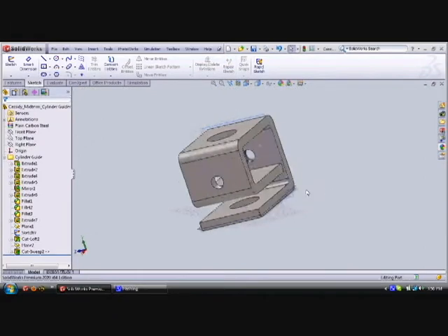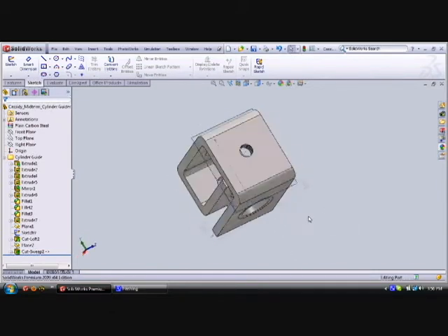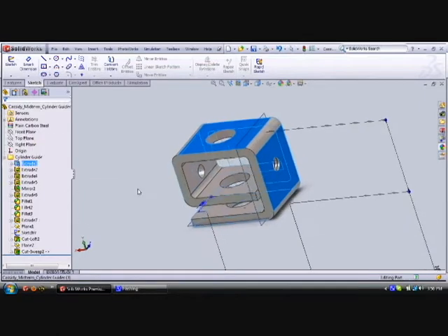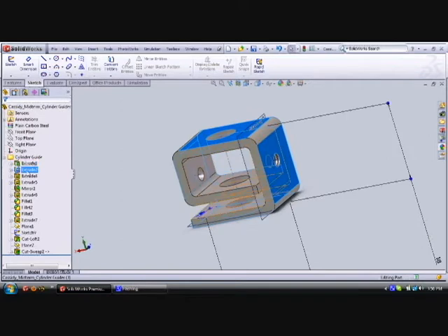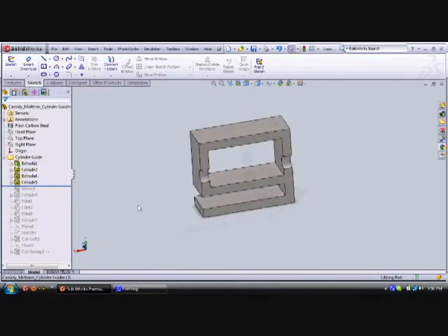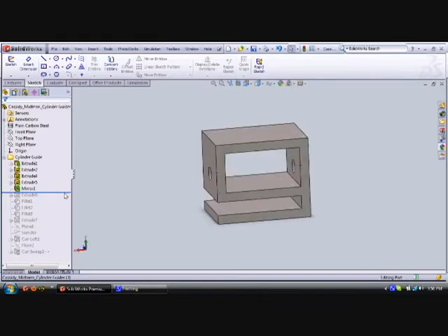The next part I designed was the guide for the cylinder. The cylinder runs through the middle, then actually cuts the paper and is screwed into place at its back. To design this, I just did an extrude of a square and then cut out the necessary pieces along one plane. I only designed half of it and then mirrored it to get the full effect.